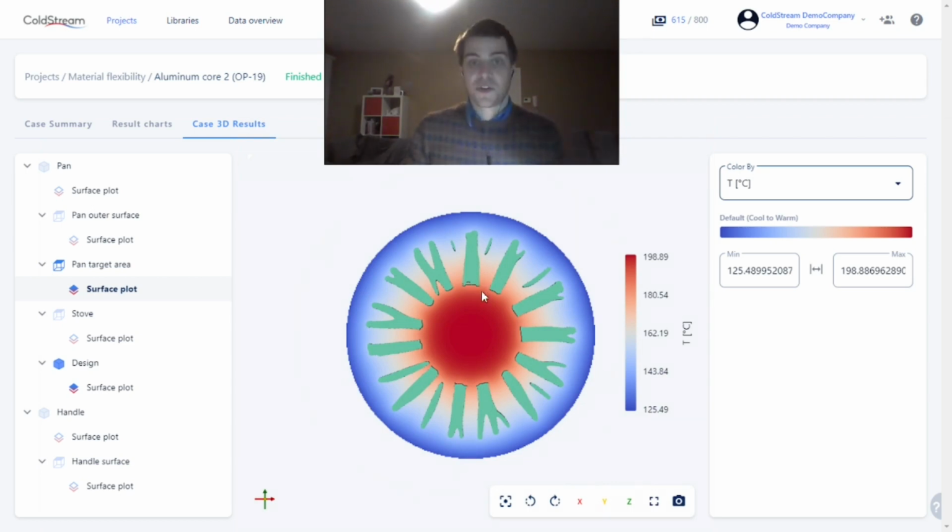And because it's more conductive than our graphite, it doesn't need as thick branches compared to the graphite itself. And again, we can see that the bottom temperature of our target surface has increased once more. So we started from around 96 with our empty control. We moved to 117 with our graphite arms. And when we use aluminum, so with our longer but more narrow aluminum branches, we increased from 117 to 125 degrees.